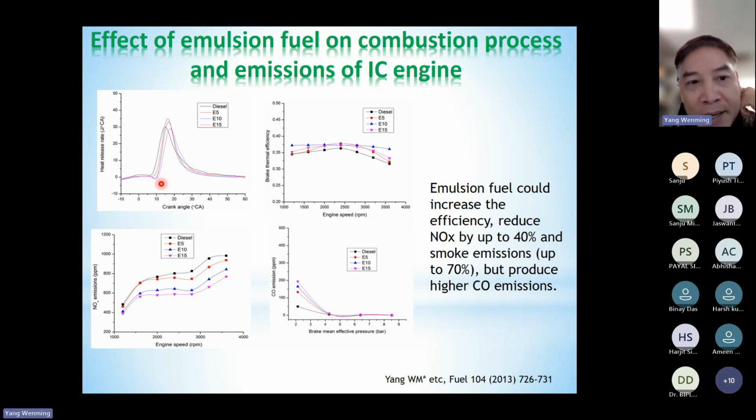Okay, it's okay. Because when the water evaporates, which means water will absorb heat energy, correct? So which means we bring down the temperature in the combustion chamber. Thereby when the temperature drops, the ignition delay will become longer.